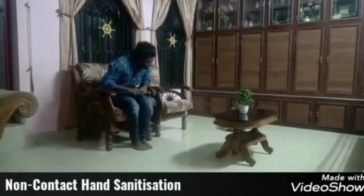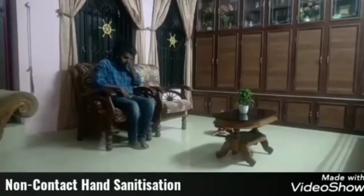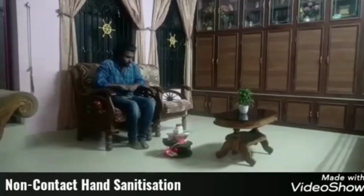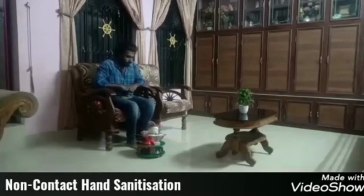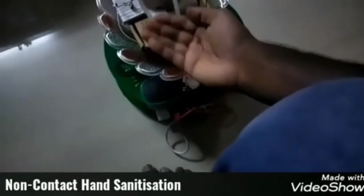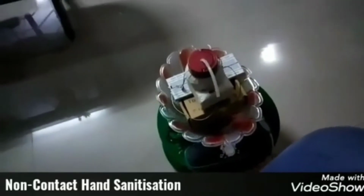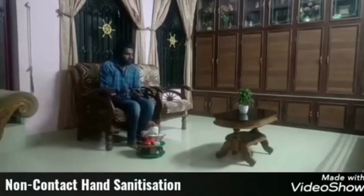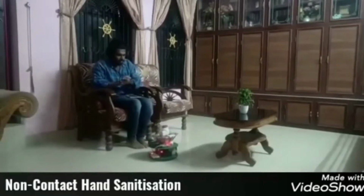Next is the non-contact hand sanitation. The robot will plan a path to the room. If the patient wants to sanitize his hands, he can show his hands under the tube for getting the sanitation liquid. The air proximity sensor detects the hand, and the DC pump will pump the sanitation liquid. The nozzle attached at the end will reduce the flow.